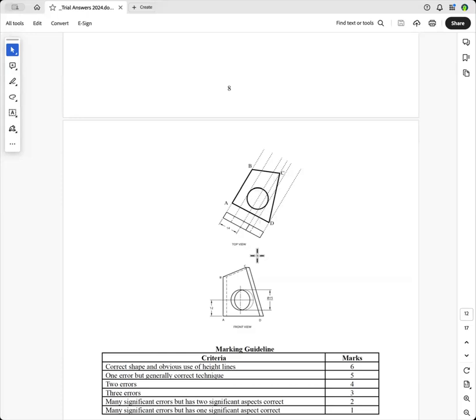Now, how do you get the circle? The circle here is a bit of an ellipse there, but you know the true length of where it sits. There's the center line of the true length going up there, of the center of the hole. And you know that that distance there is a true length. So you just mark it there, and that'll be the center for your hole.